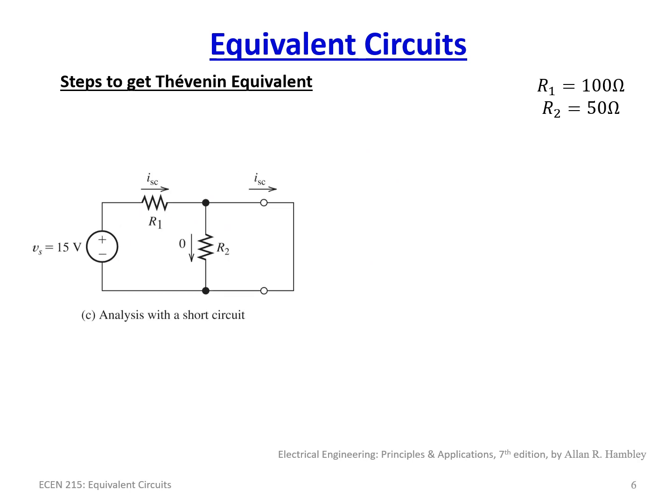The first way to get this is solving for what is known as the short circuit current, and then using that to back out the Thevenin resistance. So here, if you noticed, we have our circuit here. There's our two little terminals, A and B, if you will. And we've connected a short circuit. We literally have connected a wire between these two.